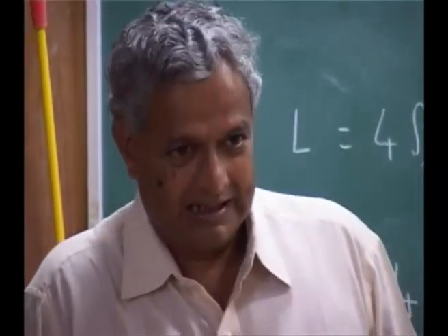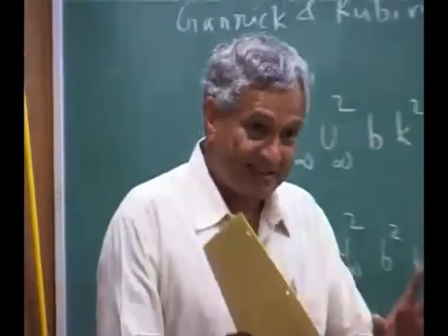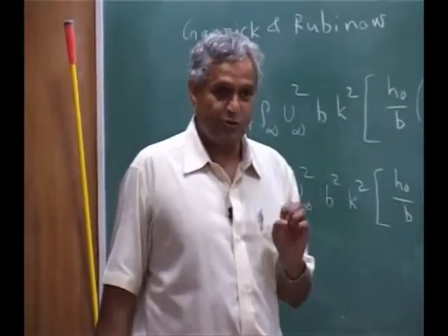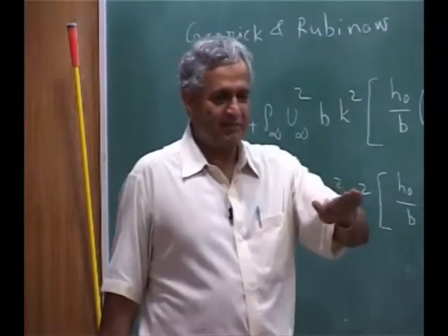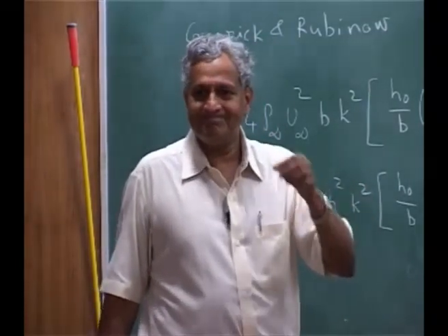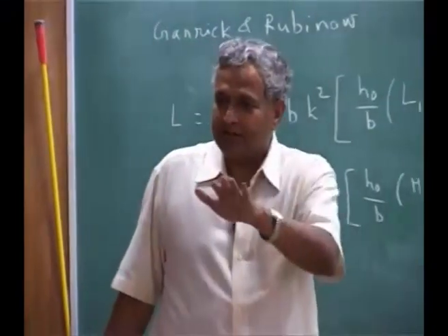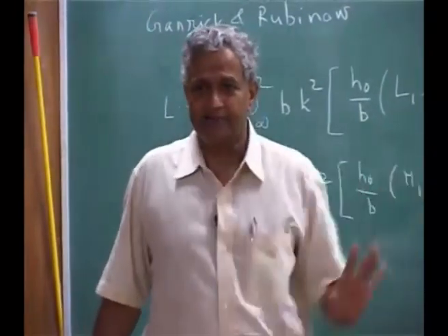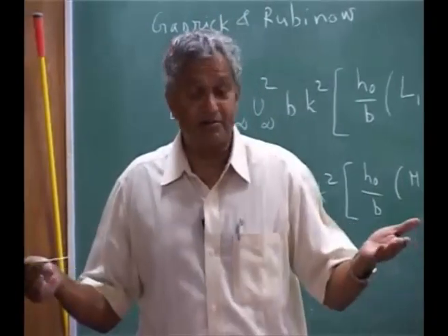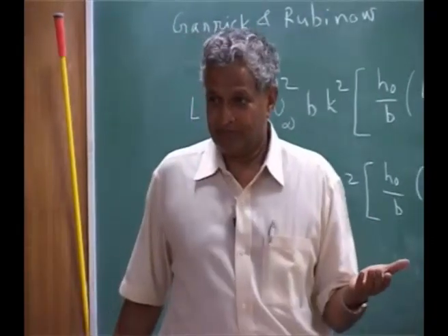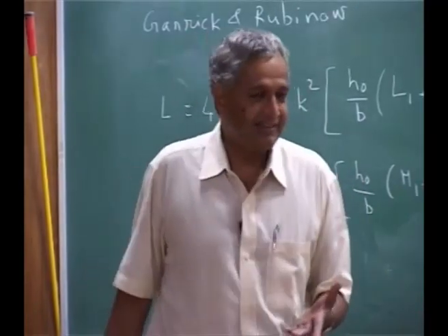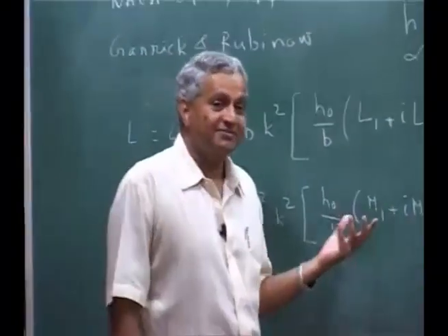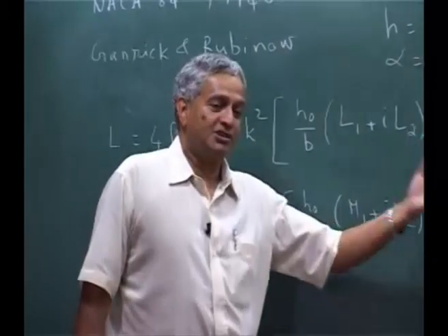That is what you basically capture, because if you assume quasi-steady, like what we said, every instantaneous angle of attack you take, you find out the lift. Then there is no phase difference between motion and lift. Whereas if you include the unsteady aerodynamic theory, then you have a phase difference between motion and lift.